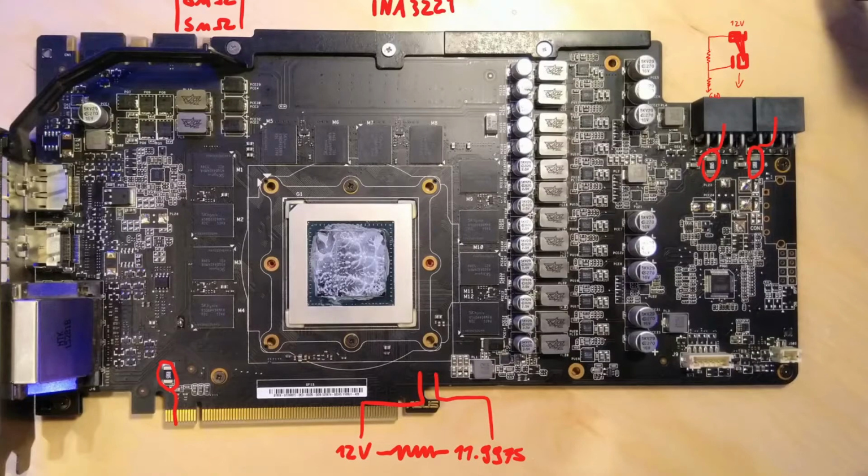So what they did is a hardware modification. So let's say on that 5 milliohm shunt, we solder an 8 milliohm shunt on top. And since we just put resistors in parallel essentially, we lower the overall resistance. So in that case, we get 3 milliohms, and 3 milliohms is lower than 5. And since we now lower the resistance, but the INA3221 still assumes the resistance is 5 milliohms, we've now tricked the INA3221 into reading a different value.